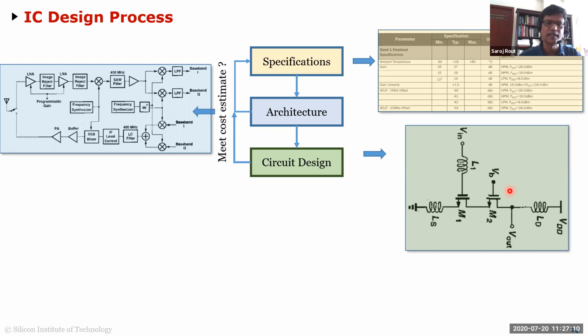What I mean by the right technology is, for example, your cell phone chip is using 7 nanometer devices, which is essentially 2 oxide atoms. I mean, they're so small. Whereas your MEMS microphone is probably 180 nanometer because that's more suitable for that analog, low-noise design. So you have to choose the right technology. Do I go for 180 nanometer TSMC?